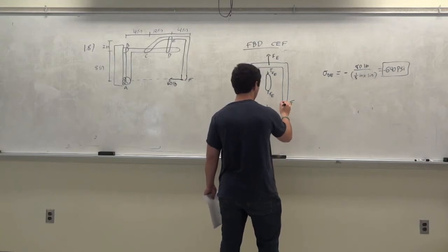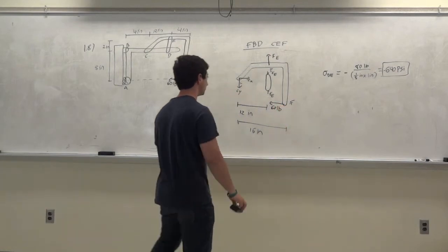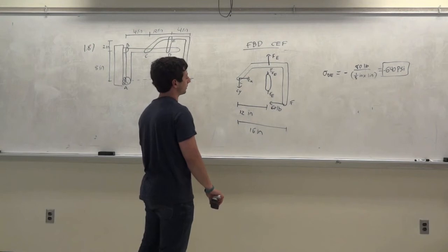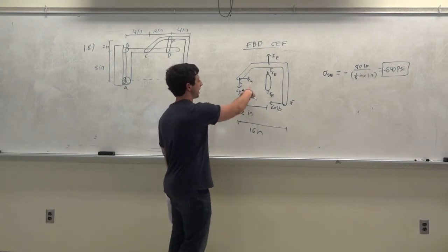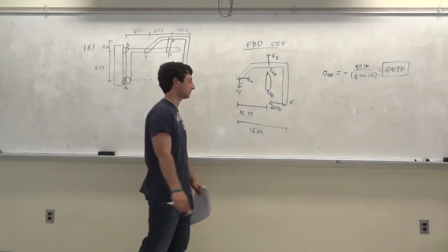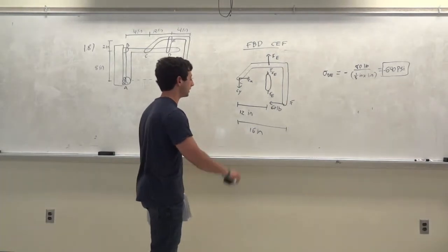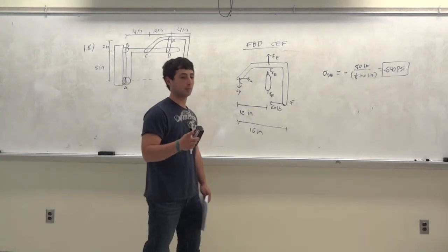So this is now to the left, it's 60 pounds. Okay, so what's going to change about this free body diagram? Nothing. Nothing's going to change. Before you didn't have a CX. CX was 0, but now you do have a CX. CX equals 60 pounds. Okay, so the free body diagram is the same, right? So the only thing that's going to change is when you sum the moments, right?